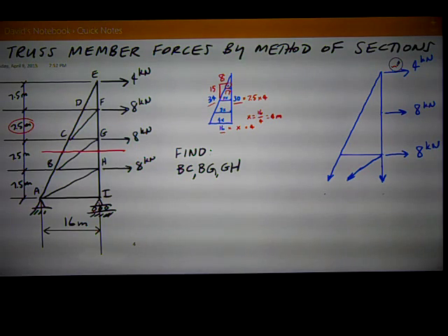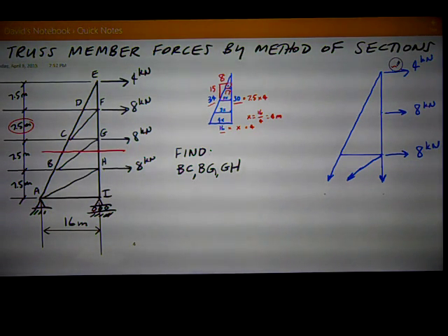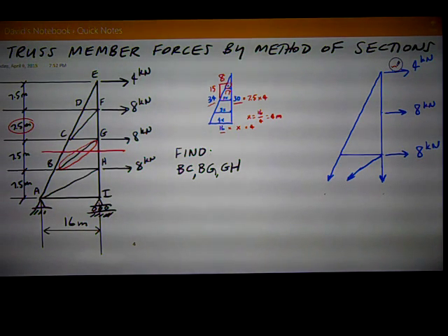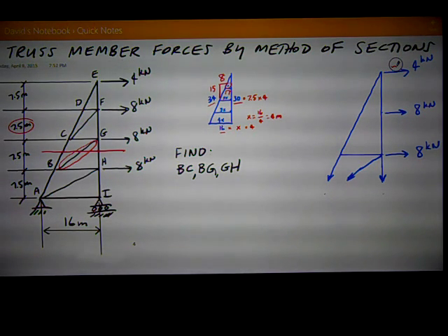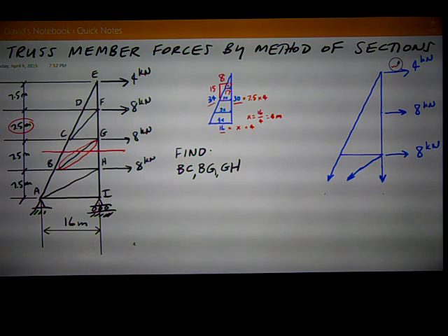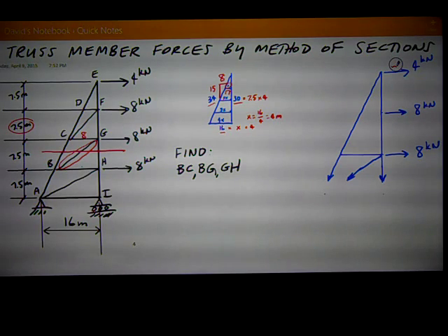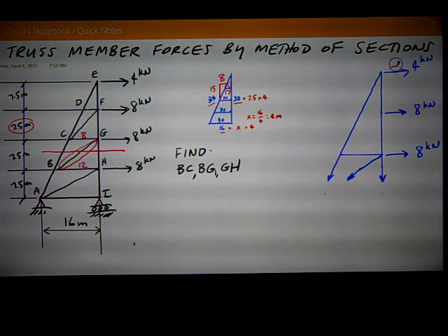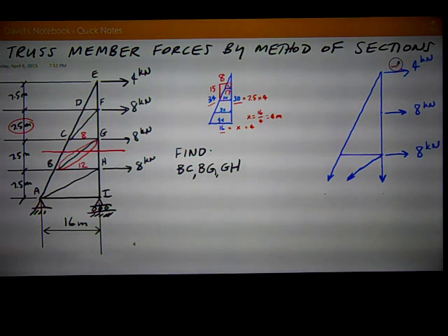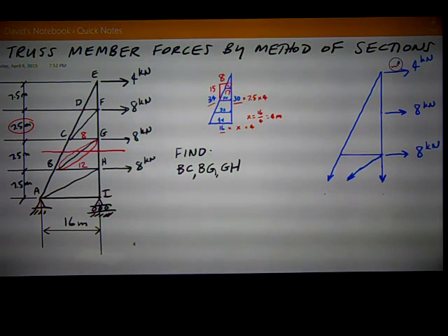Now we've also got a member that's sloping, that's a different geometry. It's member BG. So looking over here, that's one we want to focus on. What's the slope of that member? And from the similar triangles we say, well, from C to G is 8 meters, and from B to H is 12 meters. Well, we're just looking at BG on a Cartesian coordinate system. It's going over 12 in the x direction and up 7.5.